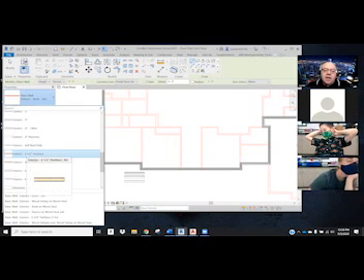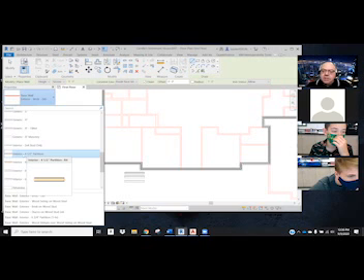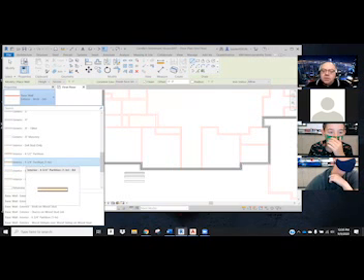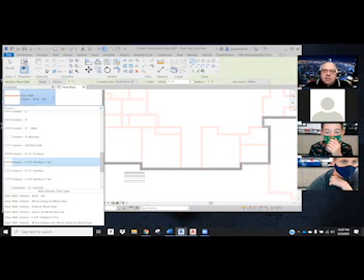Then we have a 4.5 inch partition. This is for residential. So architecture 1 and 2, this is your interior wall. Architecture 3, this is yours. And notice it says 1 hour on it. That means this wall, because we've thickened the gypsum board thickness or the drywall thickness or the sheetrock thickness, is going to take an hour to burn through that wall.